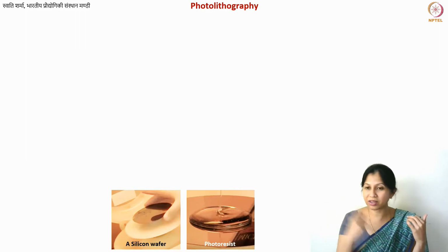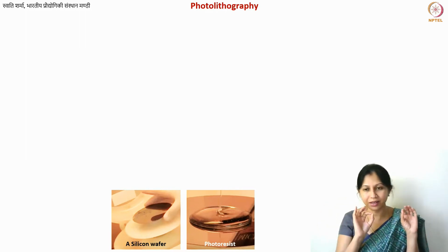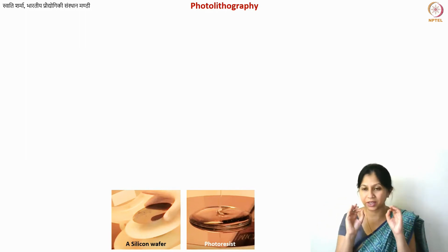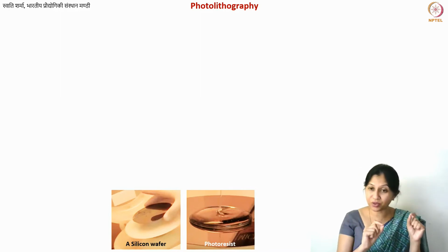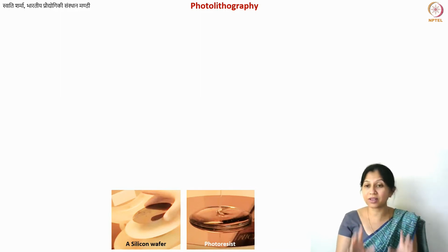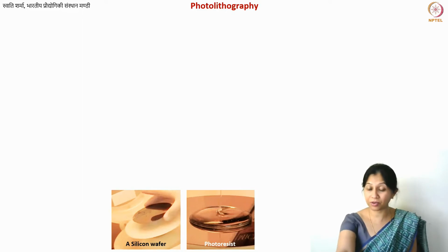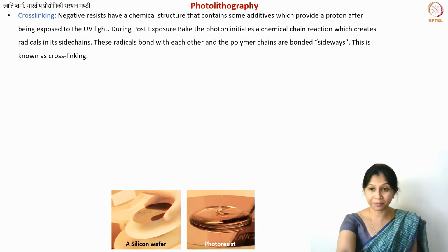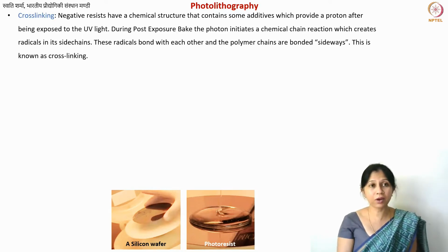So when you are spin coating, the combination of a certain resist viscosity and the rotations per minute will always give you the same film thickness, and this is a highly reproducible fabrication method. Now in this lecture, we are going to talk about some fundamental definitions that you need to know when you're performing photolithography operations, and actually any other lithographic operations as well.